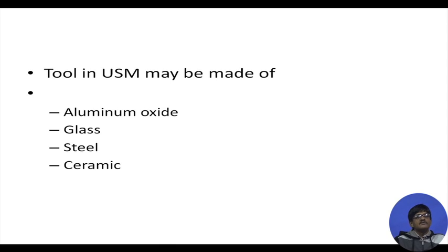If it is glass or ceramic, definitely it will take up damage. If it is aluminum oxide, then also it will take up damage because aluminum oxide is reasonably brittle. So steel must be the answer. It has to be made of steel so that it itself will not take up much damage, being basically a ductile material. Okay. And it will not crack up.